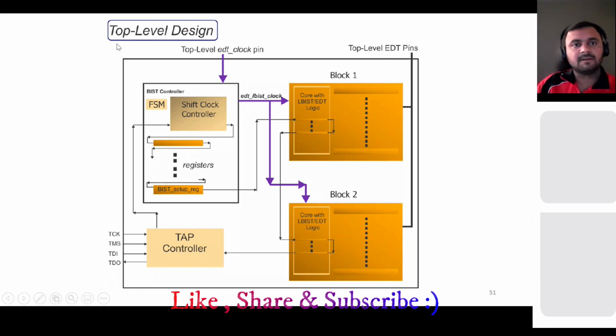So basically this is the top-level design, and then you have this LBIST. Nowadays we take LBIST along with EDT, so we are using both logics together. We have the LBIST and EDT in these two blocks, and we have this BIST controller here. From the TAP itself, we generate this control logic and test the particular block. There will also be muxes to select what to test. Suppose you don't want to test block 2 and want to test only block 1, you can bypass it, or use the muxes here to select the particular logic.